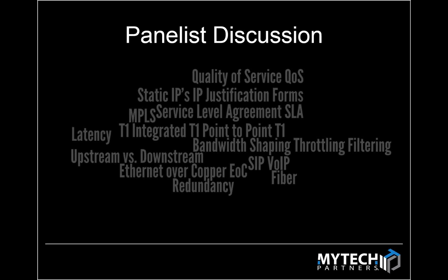Oftentimes, if a building is not on net already with a given service provider, that time delay is a minimum of 90 days, if not 6 months, to bring that service in. One of the issues we have here in the Minnesota market is permitting for winter construction. Most cities will not allow digs to be conducted during winter months, and so all construction goes on hold until April 1st, until the frost is out of the ground.